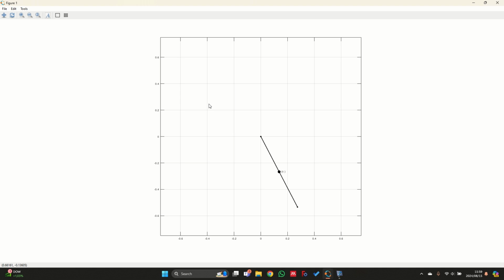At this point, we can see it's now reaching zero velocity. Then the torque picks it up a bit, and then it's probably going to fall again. So we're going to have this sort of oscillatory motion over here the entire time due to the torque not being sufficient for rotational acceleration in the counterclockwise direction. Okay, there we can once again see that's the maximum height that it's going to reach, and then weight is going to counteract that torque again, and it's going to dominate the actual motion of the system.